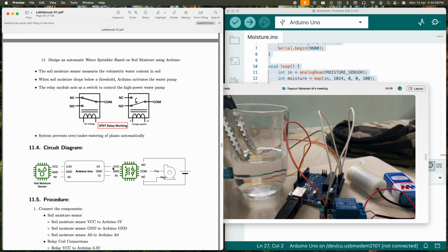So this is the relay. Now, how is this relay activated? That relay is activated by our Arduino Uno. You have the VCC, ground, and you have the IN pin using pin 13. Whenever we want the relay to be activated, or this pole to be thrown to the normally open, that is, the motor to be switched on using the external source, what we do is we activate pin number 13.